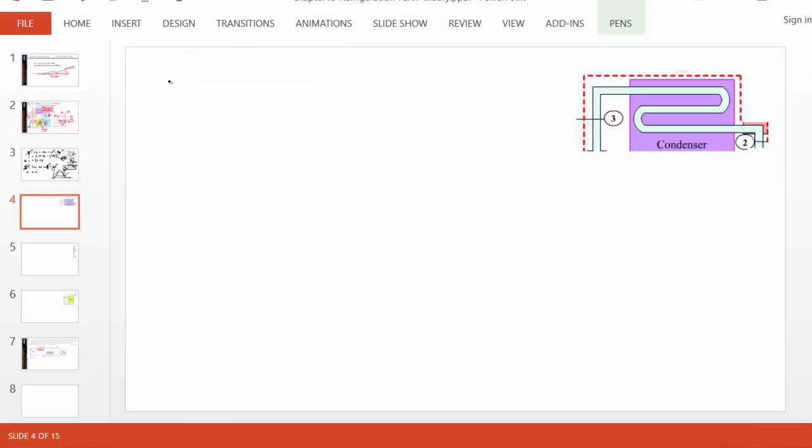Again, let's quickly use the energy equation. In a condenser, heat is coming out, Q dot out or Q dot H, whatever you want to call it. So energy that goes in, energy that comes out, Q dot H will be the difference between that, and you can practically write it without going into the energy equation. What is Q dot H? The energy that goes in is higher than the energy that comes out with the flow. So the difference must be heat that is coming out, Q dot H or Q dot out, whatever way you want to describe it.